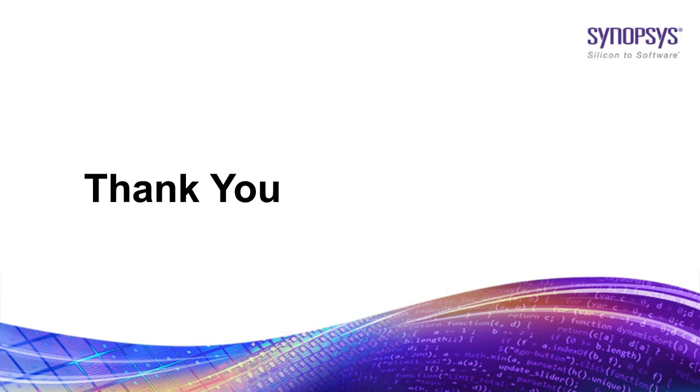But as you know, the memories have different performances and different needs for testability. In this case, we're talking about the automotive industry, where we have a very high level of expectation, very low DPPM, almost zero DPPM. Therefore, we recommend having strong algorithms to cover that. Now, if we were in other applications, gaming, let's say, where the quality requirements are lesser, then we do have other algorithms that we recommend.